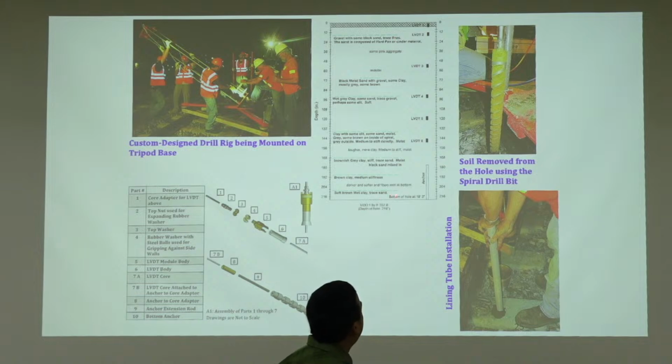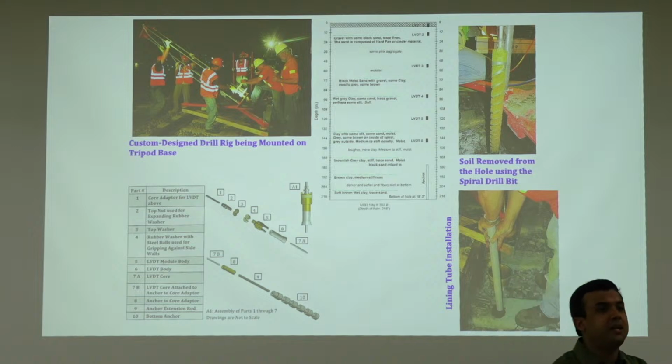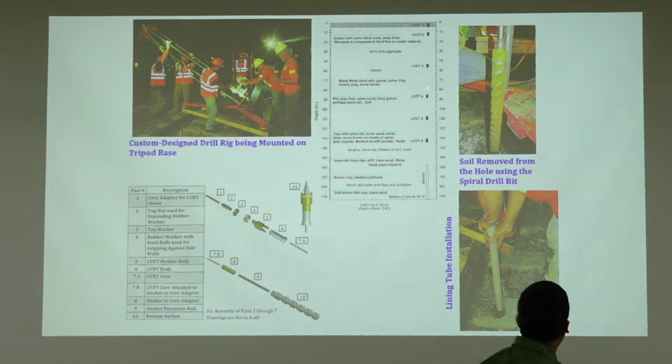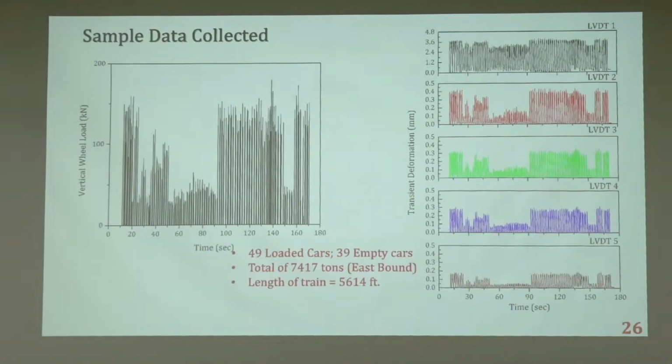When we encounter different material, we make a note, we take measurements. So it's a live bore log, and then you go back to the hotel and say, okay, my layer 1 was this many inches, so the first LVDT will be here, second LVDT will be here. You decide, and then next day you come to the field and install it.